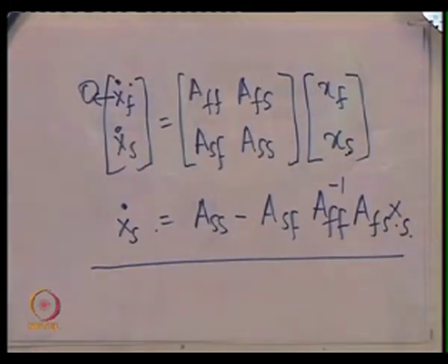I will show you the code for it. I am doing the simulation of a reduced order system in which I have treated psi d and psi q as fast variables and converted the differential equations corresponding to these fast equations into algebraic equations, and then studied a lower order system. Okay. So, I will just look at the code which does this.